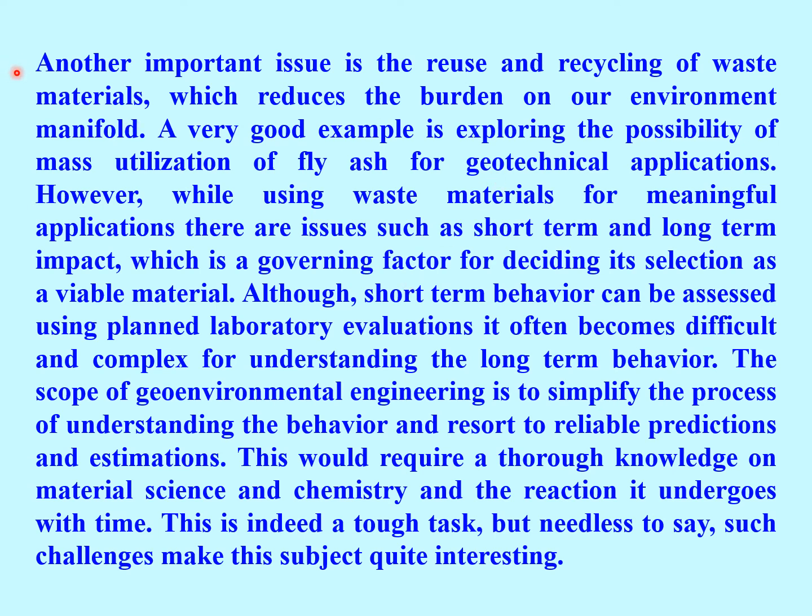Another important issue is the reuse and recycling of waste materials, which reduces the burden on our environment manifold. A very good example is exploring the possibility of mass utilization of fly ash for geotechnical applications. However, while using waste materials for meaningful application, there are issues such as short-term and long-term impact, which is a governing factor for deciding its selection as a viable material.